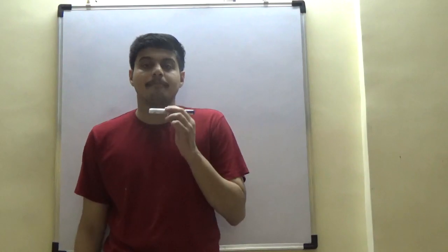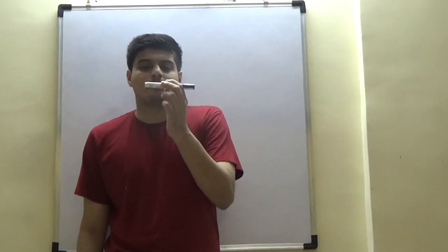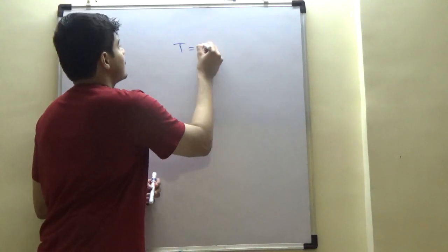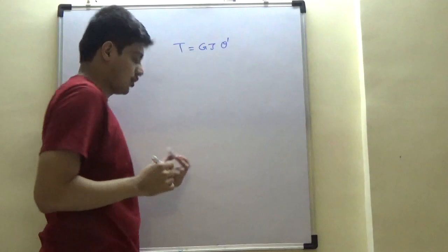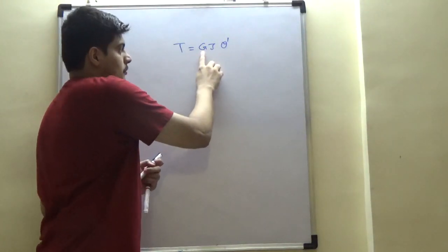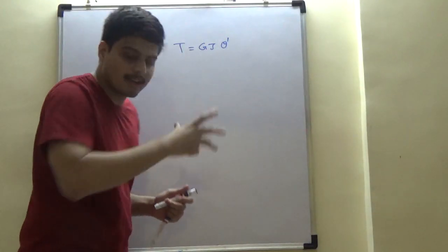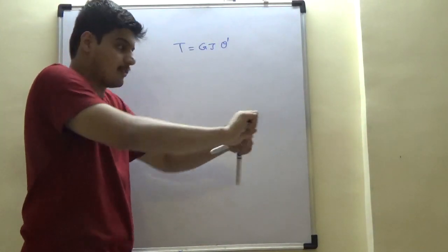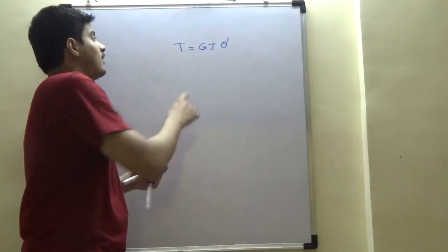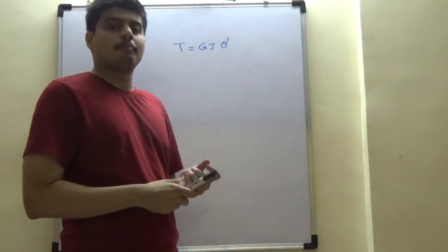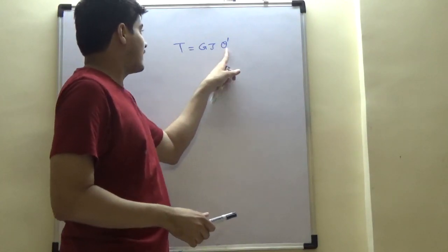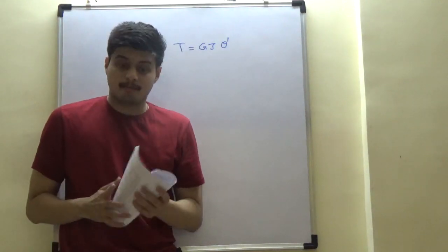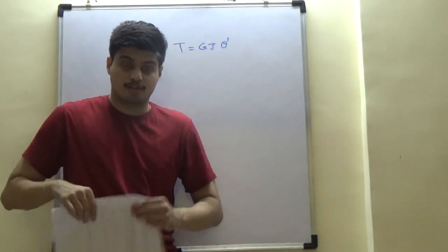as a more important point. Just to summarize one concept, we looked at this concept of torsional rigidity, right? Where we use this equation T is equal to G J theta dash, where this is a constant, this is a material property, and this is a loading condition. What we basically said is for a given twist, J is of extremely important value because that dictates how much twist is going to happen. And this is extremely important in terms of aircraft structures, by the way.